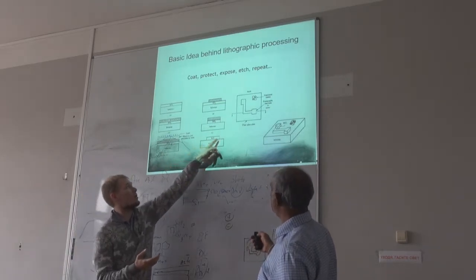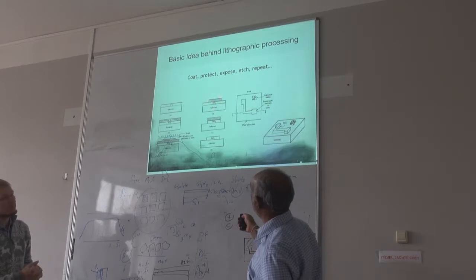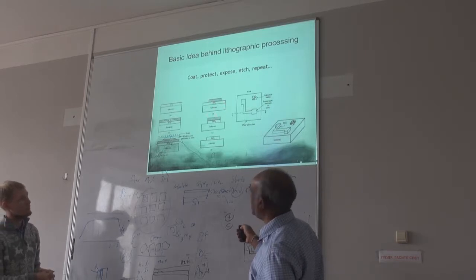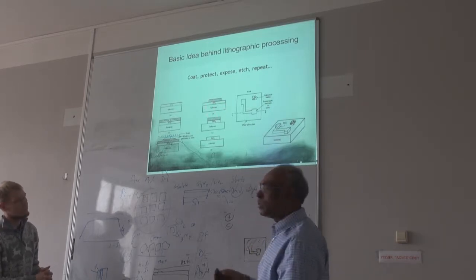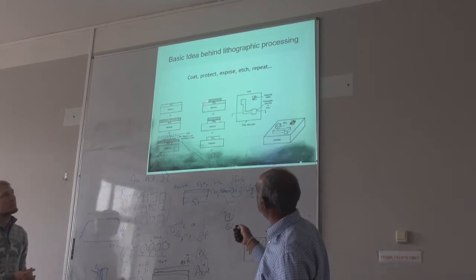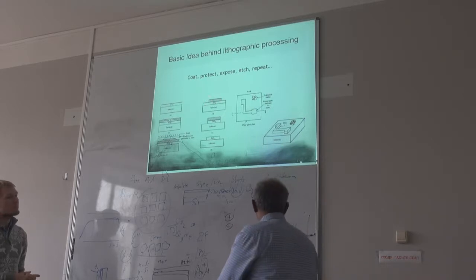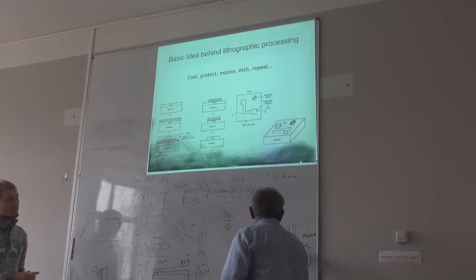So after this, after developing, we do the etching. Etch means, because this is a sacrificial layer, SiO2, you can etch this part, because only this part is protected. So only this part gets etched out here.